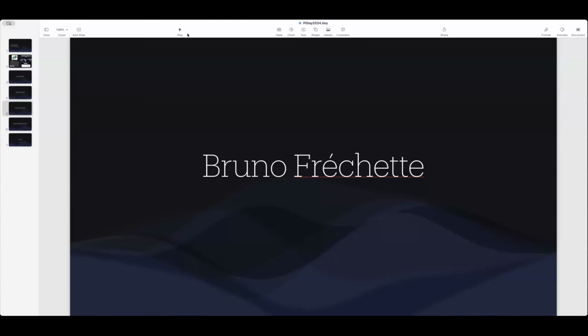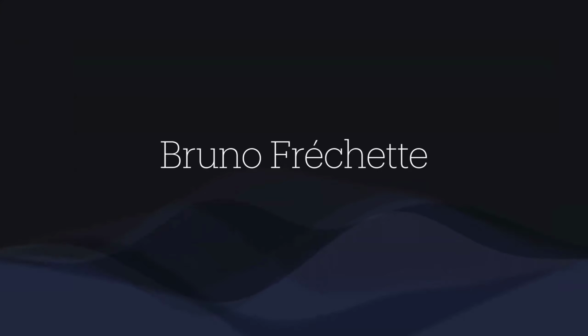Bruno, maybe I missed something, but how does the Pi know that it's lost power and needs to use the other board to do the smooth shutdown? Well, the supercapacitor board takes care of that. So the power is actually not connected to the Pi anymore. It's connected to a connector on the supercapacitor board. And the board, when it loses power, continues powering the Pi through the GPIO pins. And so the Pi does not know it's lost power until it receives a signal from the board.